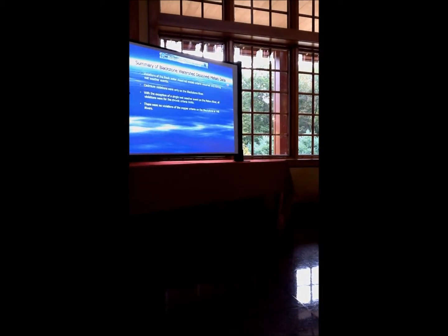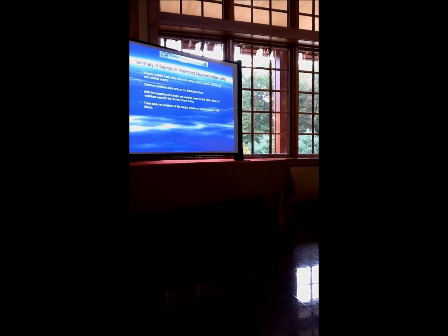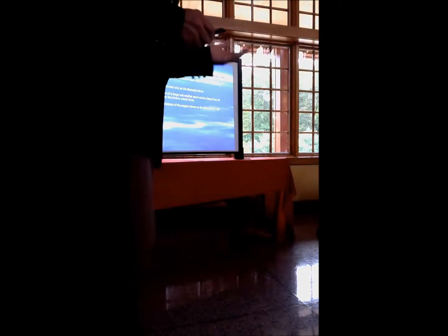Next slide, please. The summary of the dissolved metals is basically we had violations of metals criteria only during wet weather events or high flow events. We looked at that flow duration curve. We picked a point at 60%. 60% and below in the flow percentiles means it's starting to get the higher flows. So that's considered wet weather, high flows.